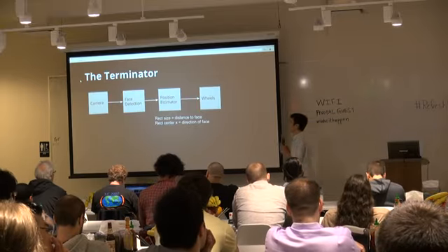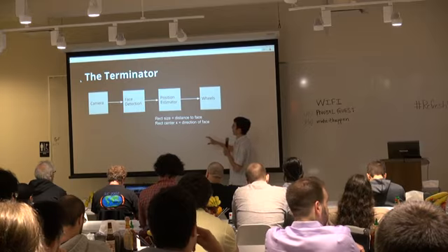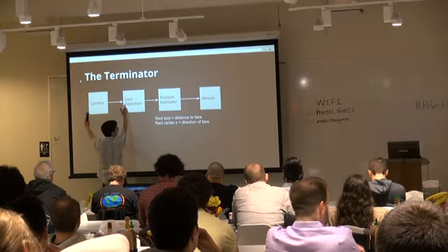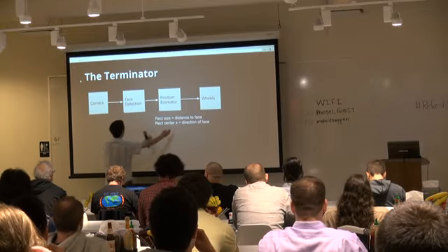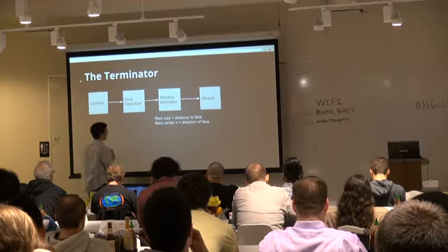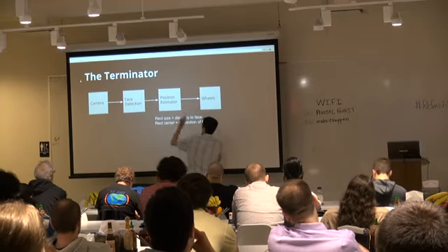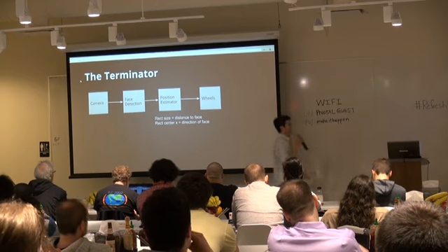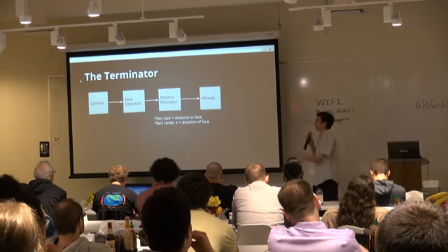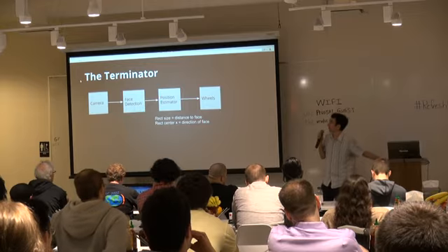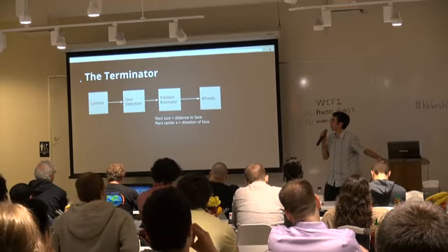When we have the rectangle of the person like over here, and the center of the image is here, then obviously we need to turn left and drive forward to get to that person. And if the rectangle is really small, it means he's far away, or she. And if it's really big, then the person is really close to us, and maybe we should stop if we don't want to run over them. It depends on the point of this robot.